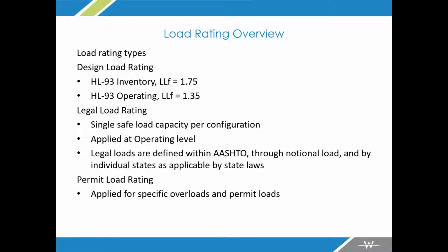So again, load rating types here, we've got inventory and operating, and those carry the different factors as discussed. We're going to look at a single safe load capacity per configuration for the legal loads. Again, those are at operating level typically. Some states can modify that. They may ask you to do it at inventory level as well. Just going by the general FHWA model for the United States, that's typically how it goes. And then the permit load rating would be applied to specific overloads or permit loads, usually by your state DOT, Department of Bridge Management, or whatever their equivalent is.